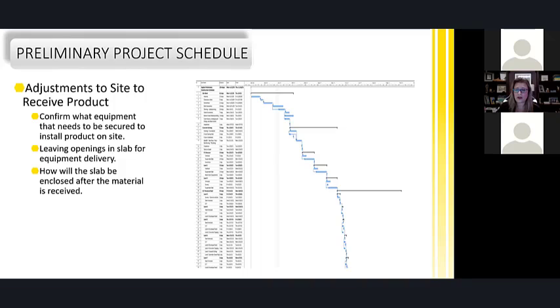So for us to come back and put a generator in a slab that was forgotten by the team was basically, we had to get rid of the CLT in that location and put in a formwork slab, because it's just impossible to be able to get a crane in there inside and deliver the CLT on that particular level. It's just things you need to consider. The mistakes that we made, you shouldn't get to make. I should be able to give you that information.